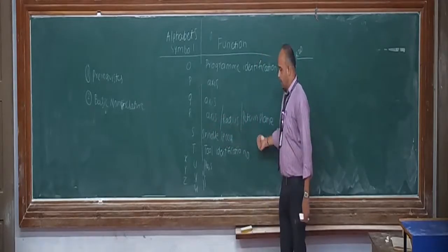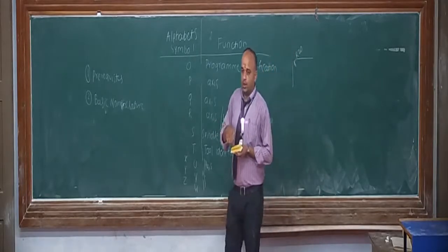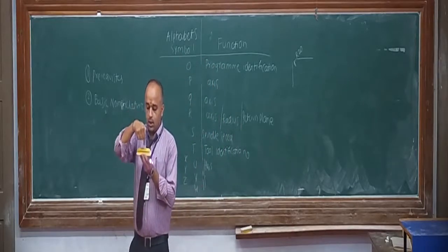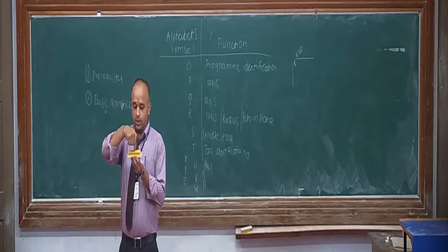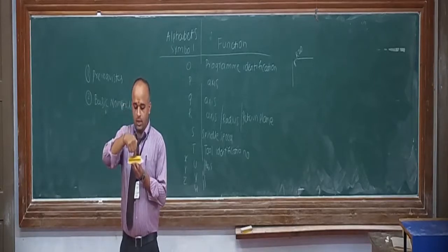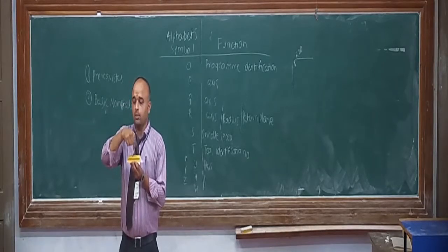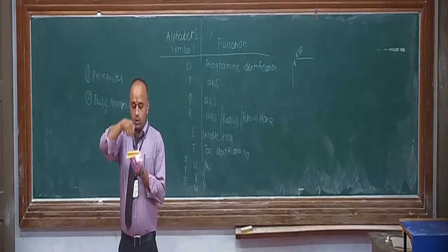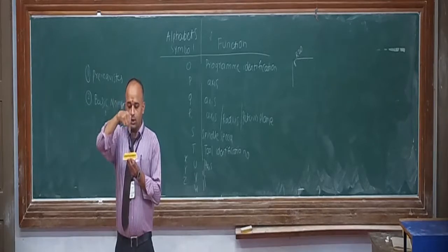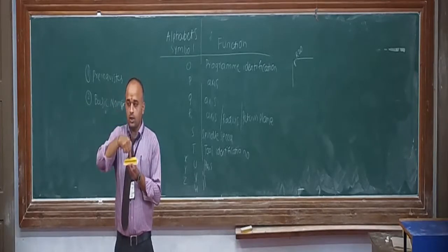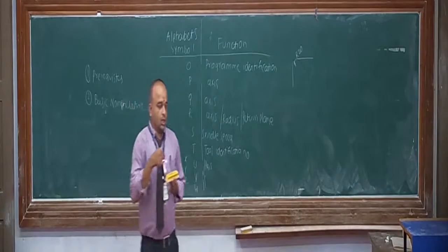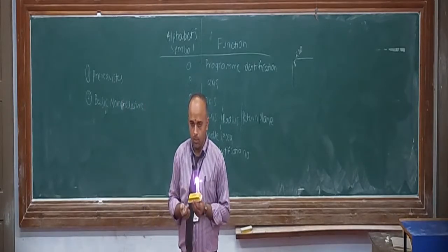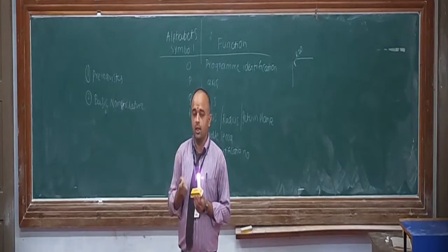Then the return plane. What is the return plane? During drilling or boring operations, the cutting tool will come and touch the workpiece, do the drilling operation, and then come back and stand at some standard point. Suppose I want to drill a hole. I do not take the cutting tool and touch the workpiece and then start the operation, because there is every possibility that the drill tip might break.